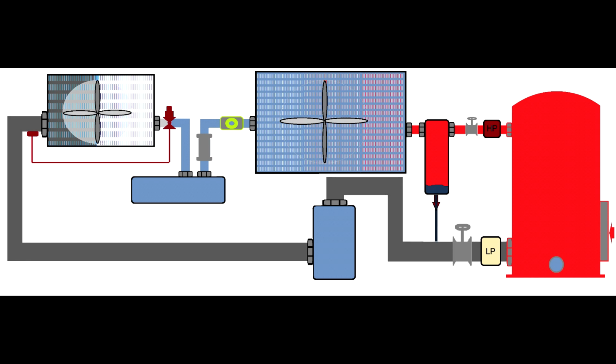But many systems in a commercial area use automatic reset low pressure switches. So anytime the low pressure switch stops the compressor, when the compressor stops, the refrigerant balances in the system and it will restart again. That is called short cycling. I usually put in a timer which will latch if the low pressure switch cuts the compressor more than 3 times in a specific period of time.